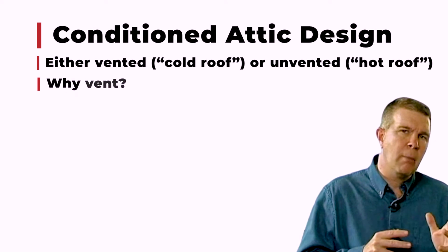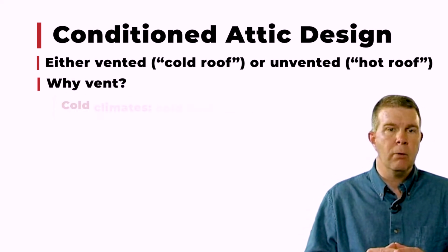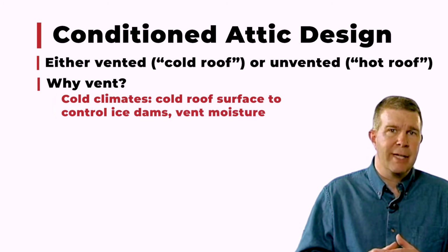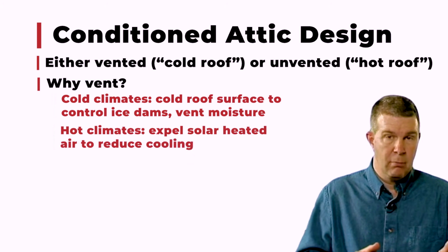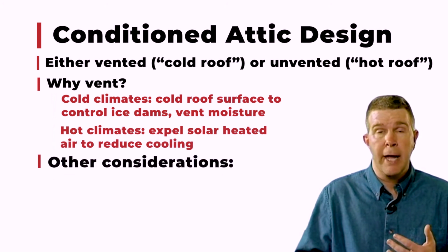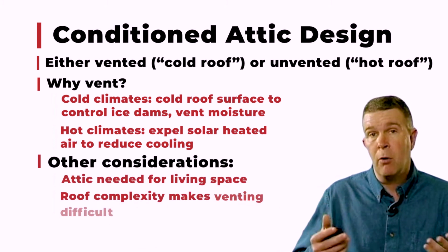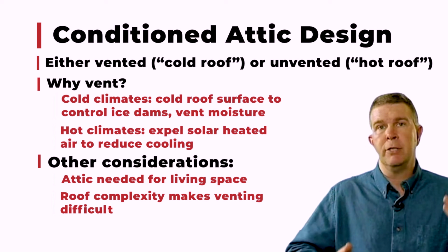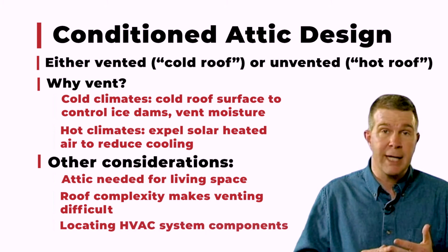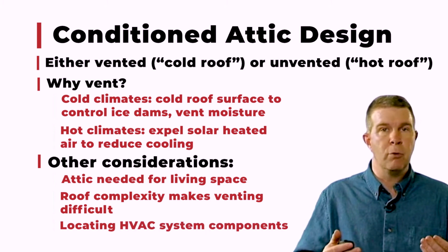First, let's talk about why we might not want to have a ventilated attic. Well, we don't want to have a ventilated attic because, one thing, it gives us more livable space, but more importantly, it allows us to take things like ductwork and our HVAC system and move them into an area where we don't have that huge differential in temperature. If we have a conditioned space, again, we don't need to worry about things like leaking ductwork. So these are the type of things that give us a huge advantage when building with SIPs.